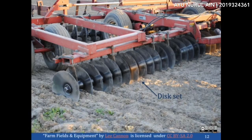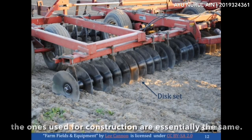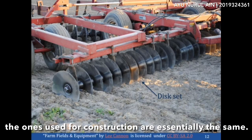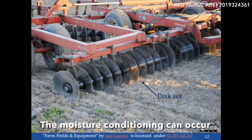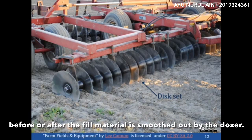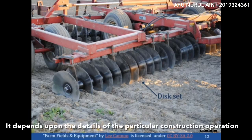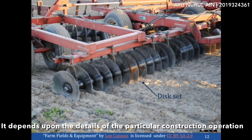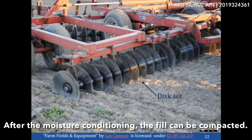Here, you can see an agricultural type disc set. The ones used for construction are essentially the same. They are pulled by a separate tractor. The moisture conditioning can occur before or after the fill material is spread out by the dozer. It depends upon the details of the particular construction operation. After the moisture conditioning, the fill can be compacted.